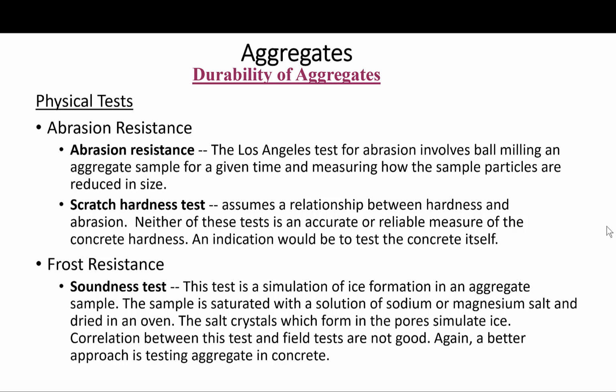We have also the frost resistance, the soundness test. This basically is a simulation of ice formation in an aggregate sample. The sample is saturated with a solution of sodium or magnesium salt and dried in an oven. The salt crystals, which form in the pores, simulate ice. Correlation between this test and field tests is not good. Again, a better approach is testing aggregate and concrete.